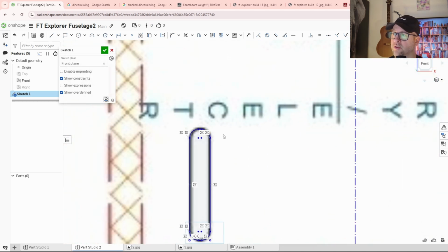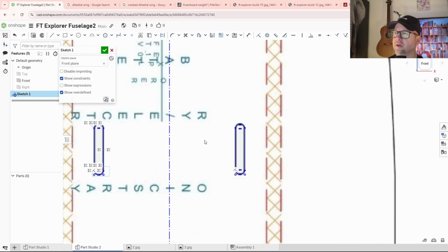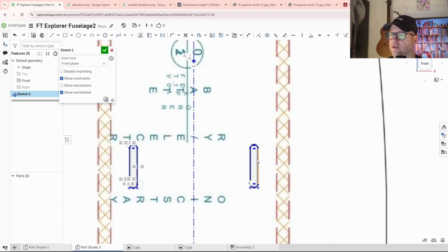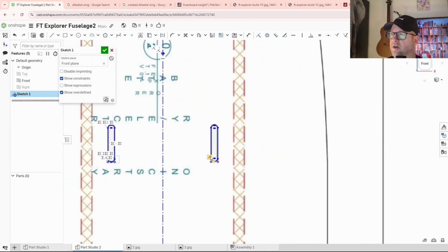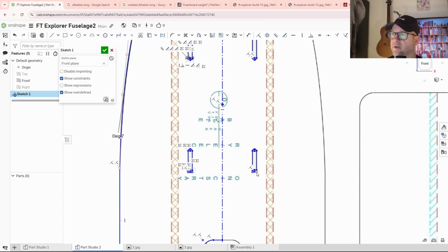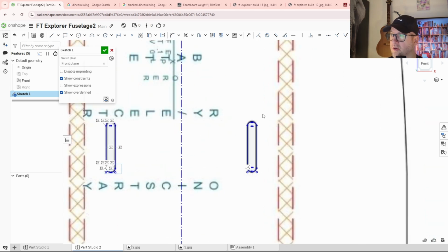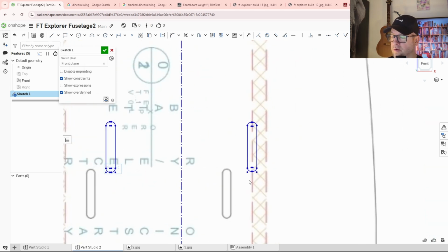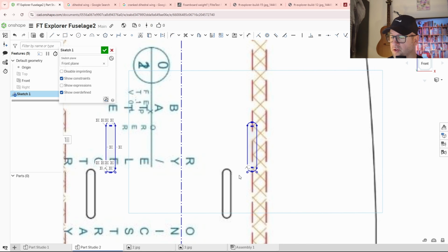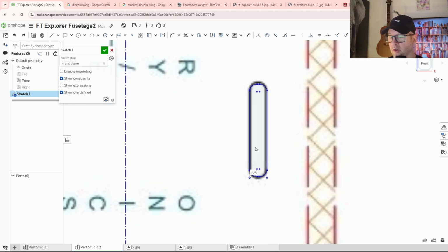Now we could just mirror that about this line if we wanted. Actually, I forgot. We don't even need this one. Never mind. Because I'm going to mirror the entire geometry. Alright, so we can just escape, hover, when you do that, you just Control Z, get back out of that. So I'm going to hit my M, and then just trim everything.